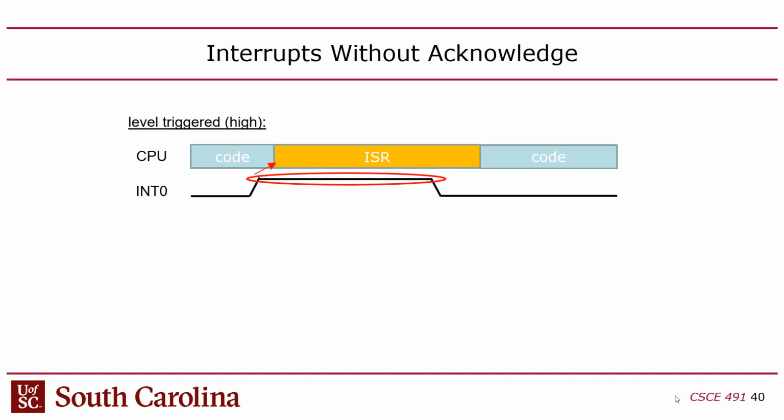Anyway, ISR stands for interrupt service routine. It's basically the code that services the interrupt, right? Typically on bare metal you would have written this, or it might be bundled inside the Arduino library or the API that you're using. Makes sense? So this is how the Atmel 328P handled it. Very simple.